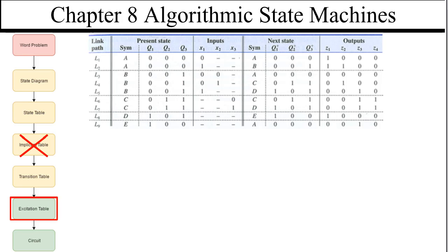Okay, so we're going to rebuild this with D flip-flops. We're going to start with the transition table, which is the same thing as the excitation table. So we're going to figure out what our D values are coming into the flip-flops. D1 is the same as Q1. And we're going to build it with a Karnaugh map that's just like we did with JKs.